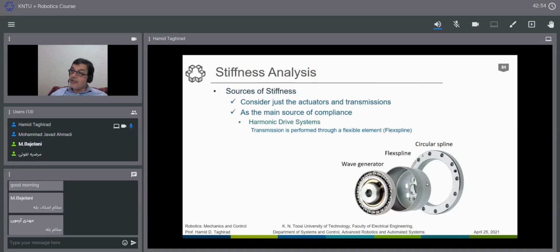And in radius, this is a bit smaller than that, with one or two gears less. It has one or two fewer gears than this one. So if you put these two together, it is somehow loose. And we have a wave generator, an elliptic ball bearing. And it is very interesting. When they put all this together, this ellipse will make the connection of these gears in the shape of an ellipse in here. You can see in this figure, you have an ellipse here.